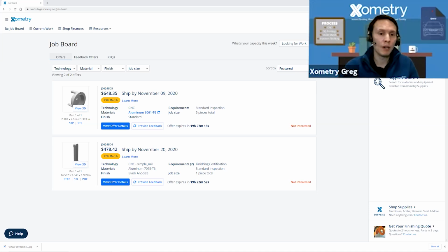So there's usually a mil spec detail that's paired with anodize, and we do have it on our FAQ. I don't have the detail off the top of my head right now of what a standard is, and it does regulate a little bit of what to expect from a type 2 or type 3 hard coat of different stages of finish. Definitely type 2 black is probably one of the most common finishes paired with 6061 aluminum. That's definitely very common there.